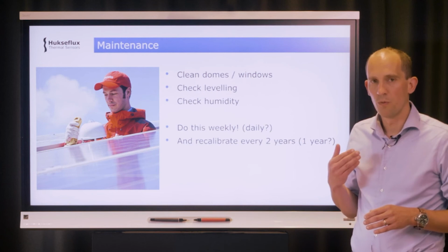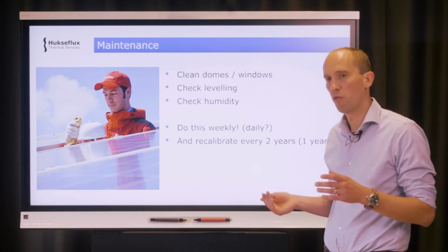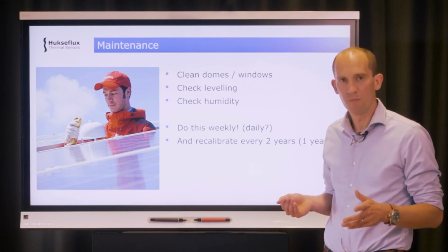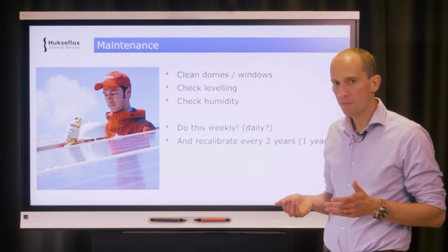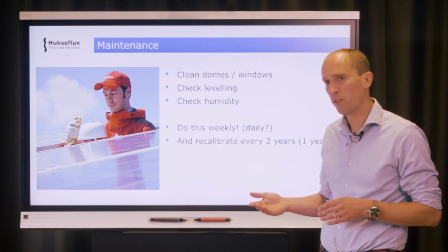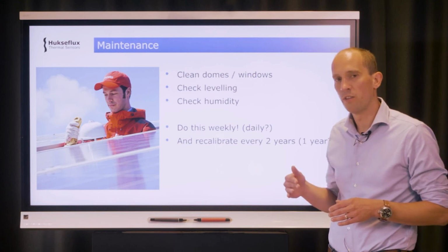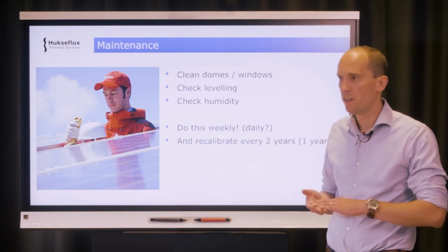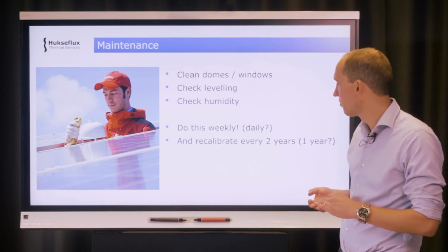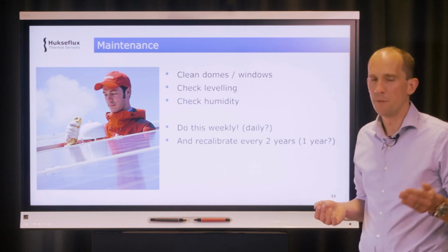Also, there is the concept of recalibration. Every 2 years, take your instrument out of the field, have it recalibrated to check whether the instrument itself is still stable. Now, pyrheliometer technology is inherently very stable, but still recalibration is a very strong way to spot errors with your instrument in the field. Many applications now move to yearly recalibration.